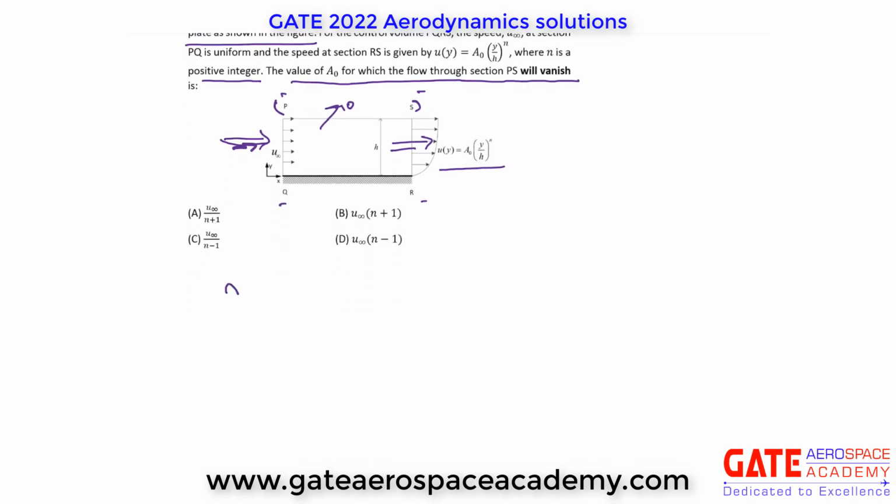Mass flow rate is rho A V, that is rho, velocity u infinity, and the area is this height h, and the width perpendicular to the screen. Let's say the width perpendicular to the screen is b, so the area will be b into h. So this is the mass flow rate entering from the left side through section PQ.